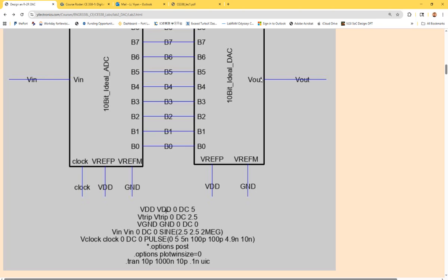For transient analysis, that's a simulation SPICE command, right? So you want to put a stimuli there, or for analysis command, which is a transient analysis, a time domain analysis, starting from 10 picoseconds to run it all the way to 1,000 nanoseconds. I think they added more arguments to this one. You don't really need that many. You just need the 3 arguments: start, stop, and resolution. That's it. This is from the example. You don't have to change anything.